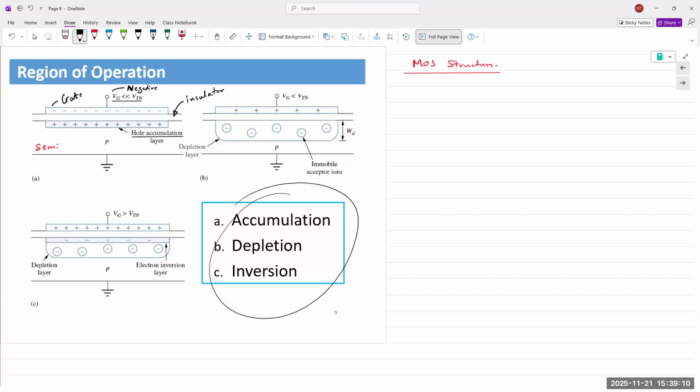But there is an insulating material that separates the semiconductor from the metal. And so they accumulate right below the gate, but they cannot cross over. This is very important. Remember when I said low power consumption? There is no actual DC current flowing through that gate terminal. It's only voltage that is being applied.